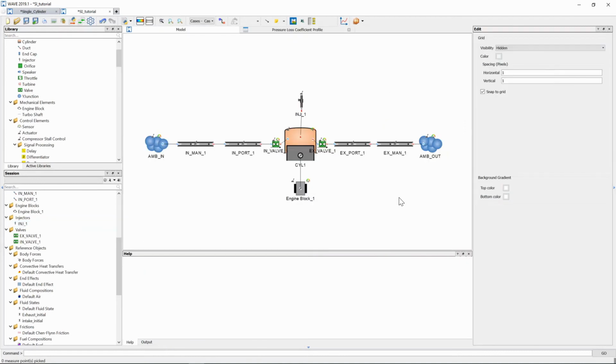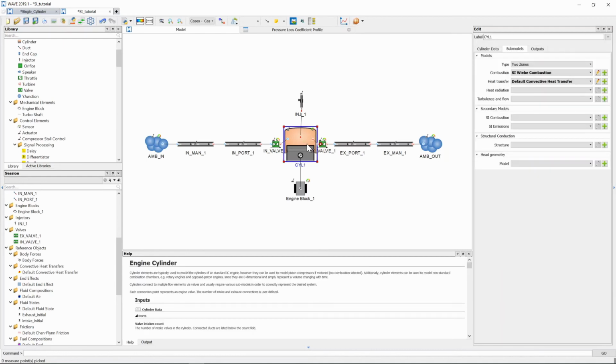Now we have successfully set up our 1-cylinder petrol engine as shown at the start of this video. Well done. But that is not all. Now that we've set it up, we need to start preparing for some results that we want to calculate. We can do this by requesting plotting for our in-cylinder pressure, because we are interested to see how the pressure profile looks like.